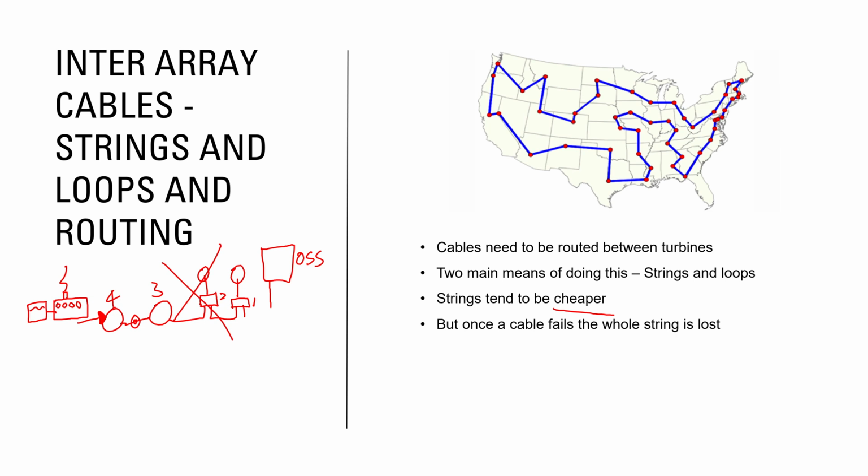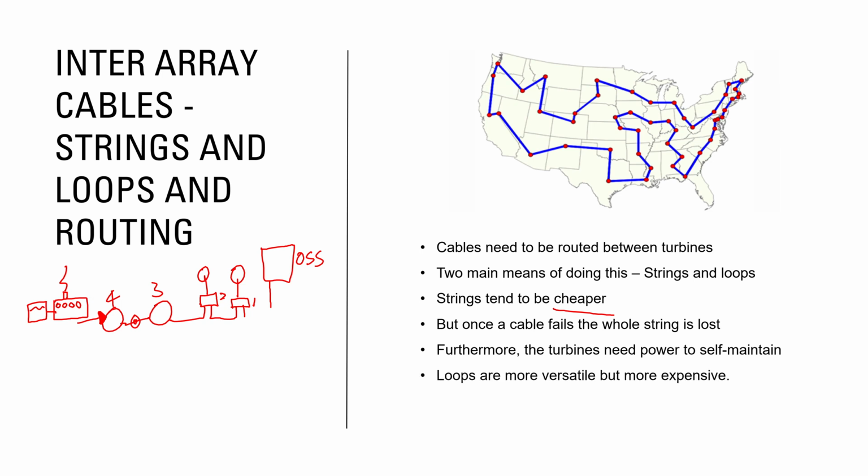For that reason, I personally, and most engineers, would prefer to use loops. Now, loops are like what in Britain you would have in a ring main in a house. But again, I appreciate that many of my international viewers, not familiar with 17th edition electrical systems, will not know what a ring main is.